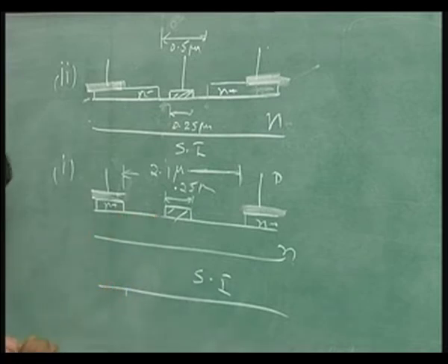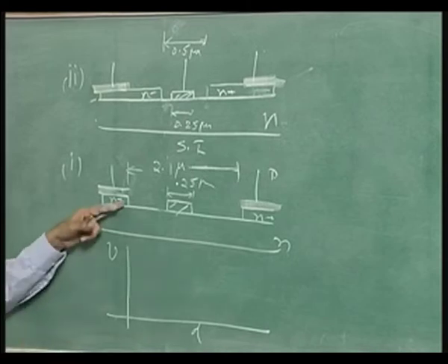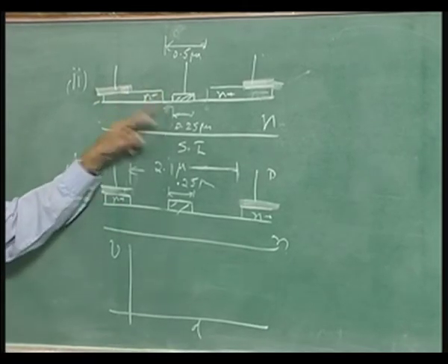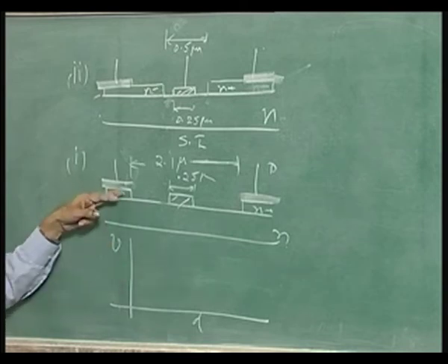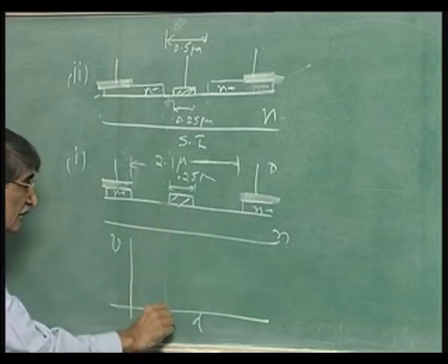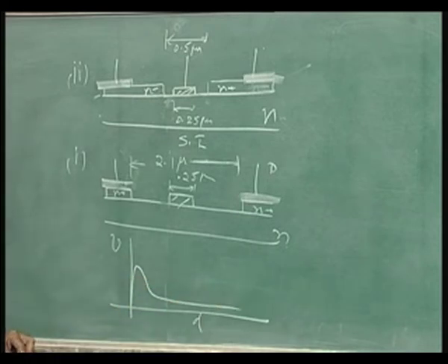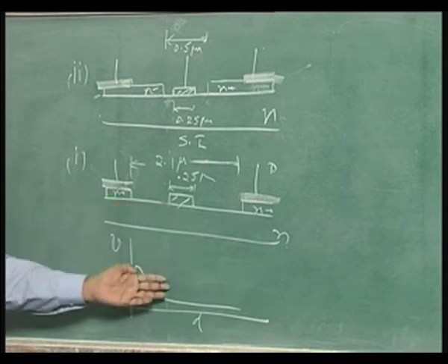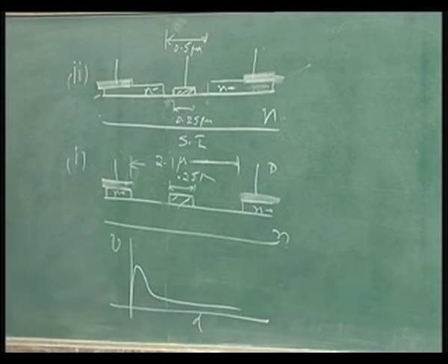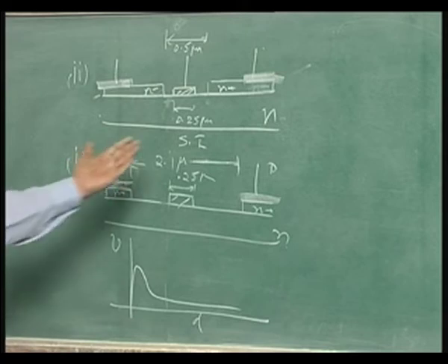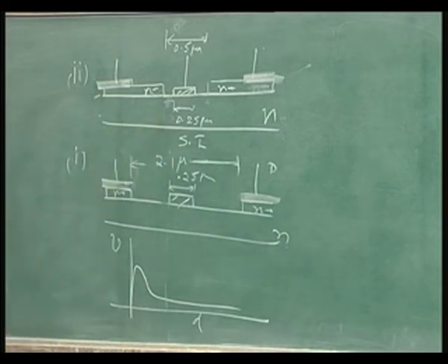So, we should plot the velocity versus distance here. Let us plot it here. The velocity versus distance, if I plot from here, see here the electrons are launched here, it is as good as metal put here, n plus layer. Here the electrons enter the channel right here, it is cold here, it gets hotter and hotter as it moves inside. So, this is about 1 micron. So, before that everything is over, it has enjoyed its overshoot effect right at the beginning. By the time it has reached the gate, it is velocity saturation. So, over most of the region under the gate, it is lower velocity. In fact, we saw it was about 1.1 into 10 to the power of 7 centimeter per second, whereas in this case the average velocity was close to 2 into 10 to the power of 7 centimeter per second, 1.9, that is what we saw. So, you can see this is a remarkable thing that we saw.